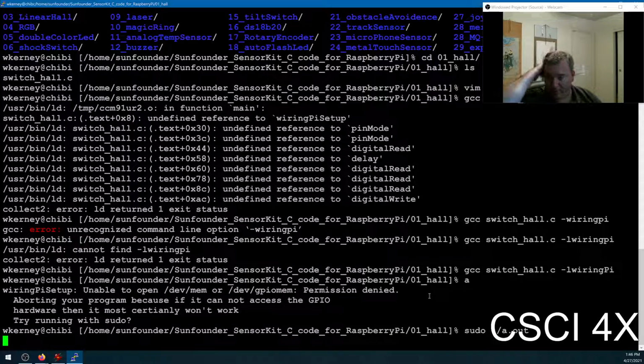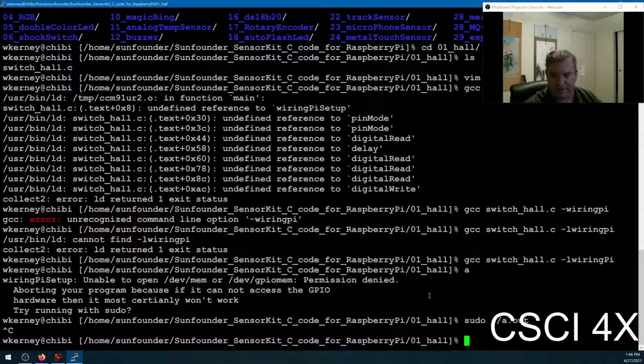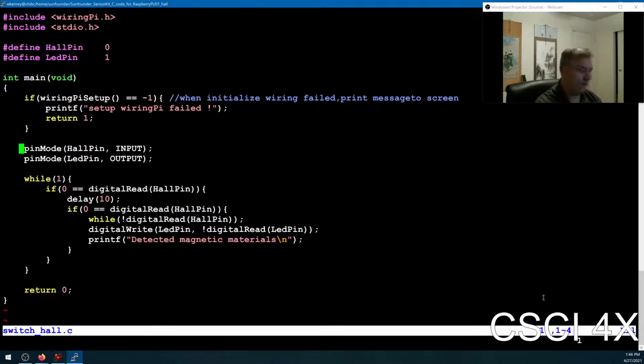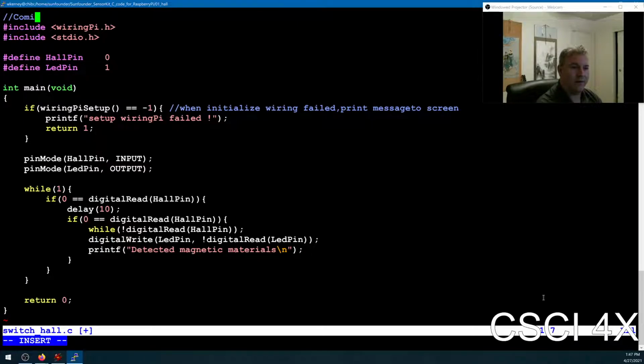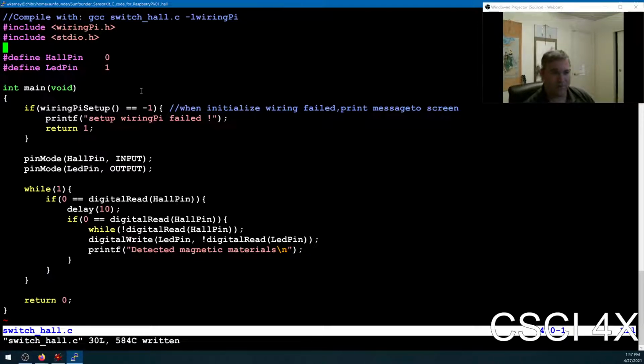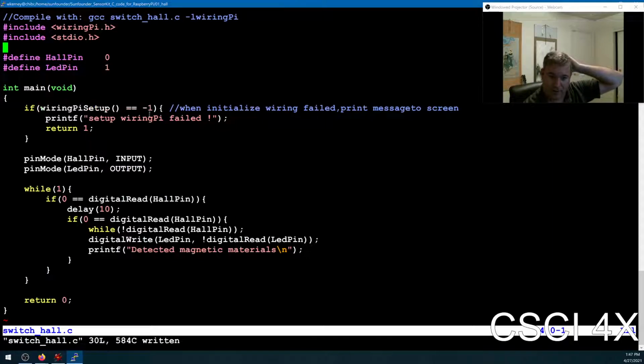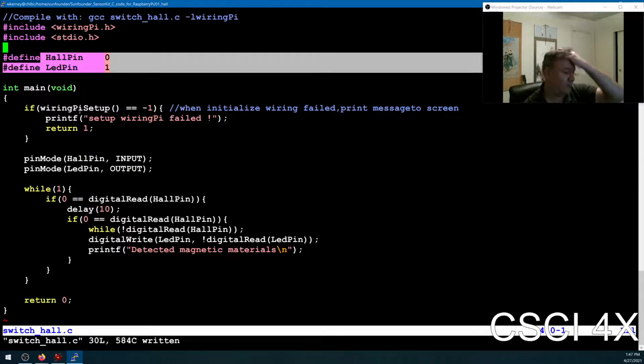So right now, the program is trying to read from the GPIO pin. Obviously, nothing is attached, so nothing's happening. But that's basically the process you go through. I should probably make a note of that in the source code. I have to look that up every time. And so, anyhow, what you do is you just include the wiringPi library, and you call setup. That gets everything initialized. You specify which pins you want to play with.